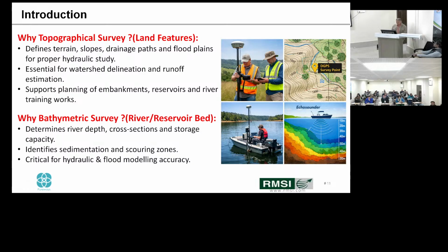Bathymetric survey is also required because it defines the real river profile and cross sections and the storage capacity, the elevation area capacity curve. And it also identifies the sedimentation and the scouring zones and also the erosion areas, which is very critical for hydraulic and flood modeling accuracy.